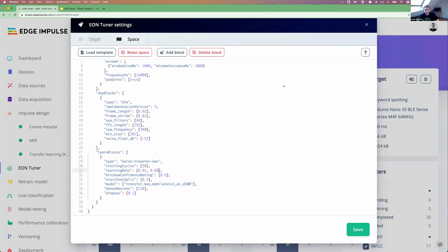I love that. When training models for sensor data like accelerometers, what machine learning techniques are possible? I would recommend using a spectral analysis DSP block, so DSP preprocessing. What spectral analysis does is detect peaks of frequencies and different things from the signal, and from that we extract meaningful features. Then you can use a really easy neural network, maybe two or three dense layers, and I've noticed that this works pretty well.